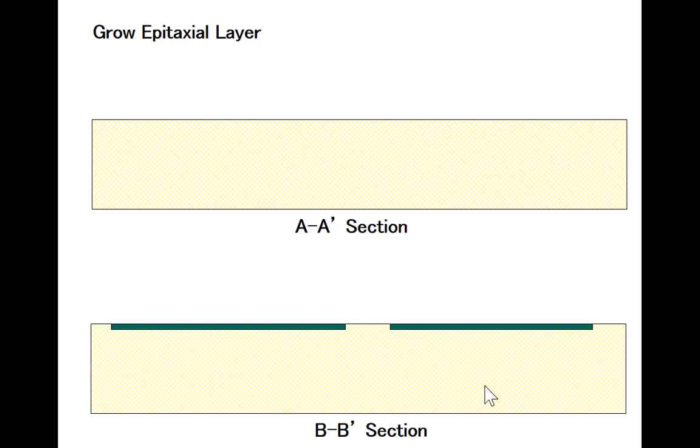But one interesting property of an epitaxial layer, and it's a property that we want when we make this bipolar transistor, is that it can be easily uniformly doped. So if we implant and diffuse, we've got a gradient to the impurities. But if we grow it as an epitaxial layer, it's uniform. Okay, so let's grow epitaxy. There's silicon all over the place. Even though we have N+ buried collector, remember, we're only a few parts in a million or a few parts in a billion impurities in this region. So it still looks like single crystalline silicon here and above. There's just a few impurities in that region.